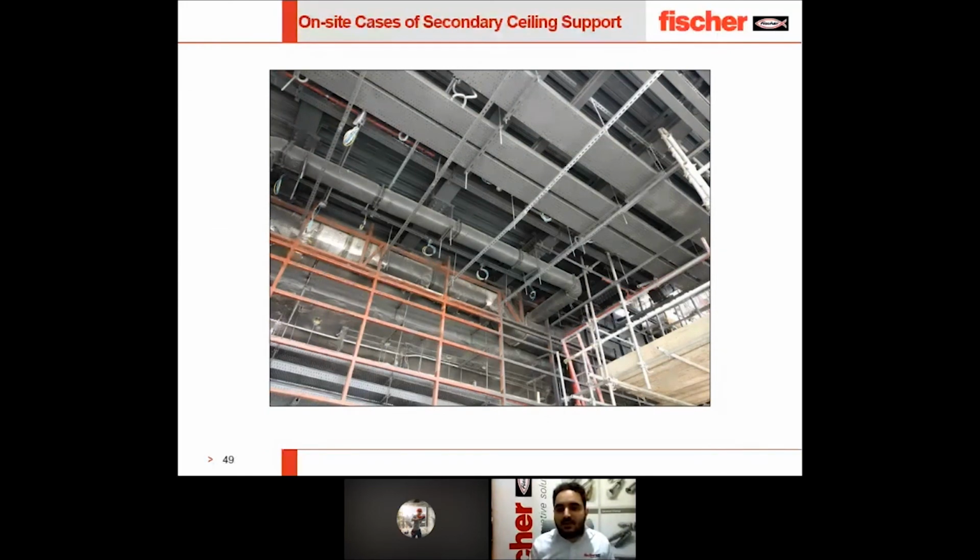How is your steel system fire rated, and how many hours? Okay, the steel itself is fire rated, as I told you. I don't have a certificate for the steel itself. My system, the Fischer fire sealant, is certified by UL. It is UL listed, and it differs by the material. It's up to 2 hours, 3 hours or 4 hours. Inshallah, if you want more detail and more knowledge about the fire stop material, we will also make a new session and a new seminar for the fire stop material and sealant.